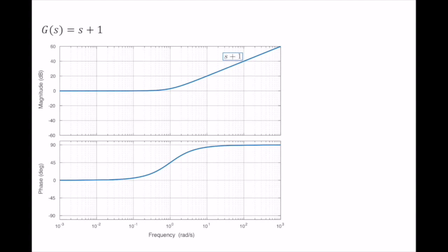It's not a transfer function, it's just kind of an identity. And this is the Bode plot. Okay, so before going to an analytic approximation, if I want to approximate this with lines, what I do is, I think at low frequencies, it's a very good line, right? So it goes like this. At high frequencies, we have a line also like this.